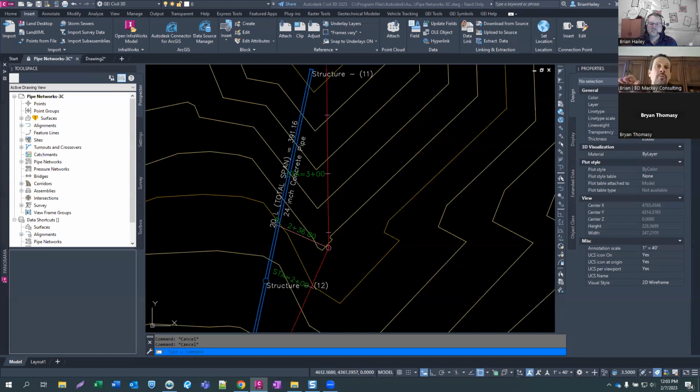Period. I don't care if I've literally done an 8x10 guard shack, I match the civil coordinates, because in my mind, it just makes life easy for everyone. So I always set that up, and I always make sure that I have an export setting that says, hey, export out to those shared coordinates in Revit, the coordinate system you guys are using. So when I give it to you, it's in feet. You don't have to scale it. It's rotated properly. Hell, it's even at the proper elevation, which might screw you even in a 2D view, I'm not sure. But I make sure I go through and do all of that. So when I give it to you guys, boom, you just put it in place.